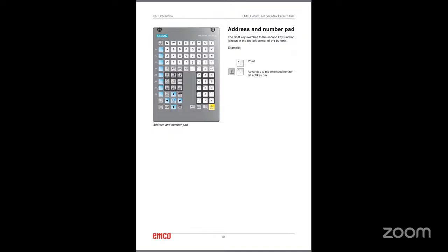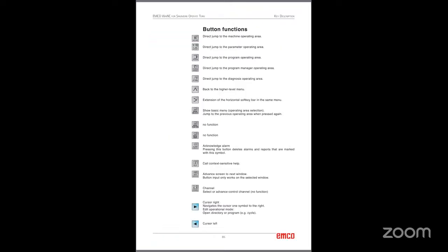So when you write the CNC program, every letter has a particular meaning, right? For example, G means motion type, X represents X coordinate, Z means Z coordinate. We call it an address. N represents the block number, to read the program very effectively, and also we can debug properly if we have the block number. G is what is called a preparatory function. G00 means rapid movement, the tool will move very fast. G01 means linear interpolation, slowly. G02 clockwise, G03 counterclockwise, G90 absolute, G91 incremental.